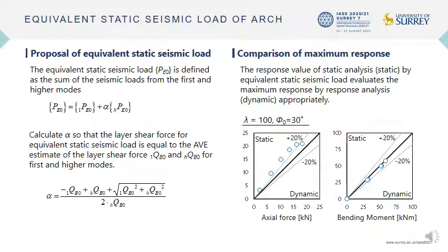The equivalent static seismic load is expressed as the sum of the seismic loads of the first and the higher mode. This figure shows a comparison between static analysis and linear dynamic analysis. The response by static analysis generally evaluates the maximum responses by dynamic response analysis.